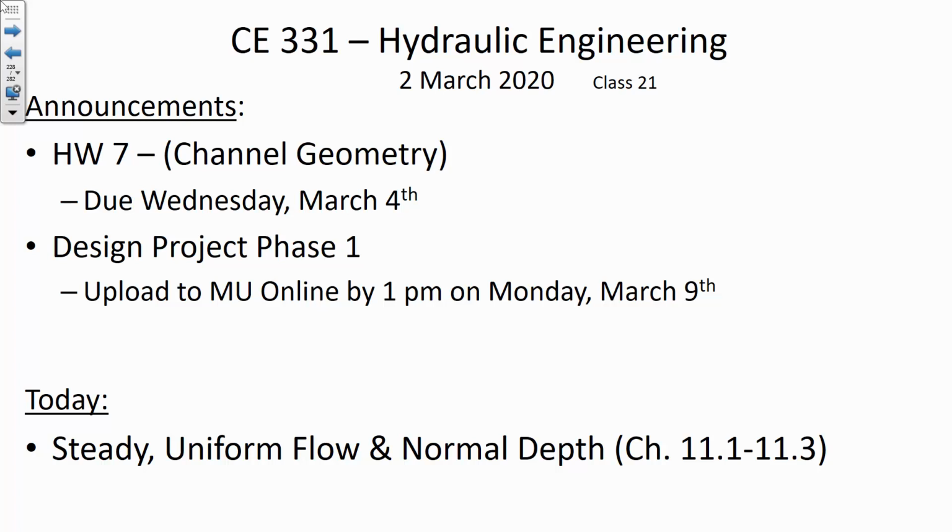So the design project is due the first phase on Monday, and that's where you're figuring out how many people are going to be in each of the zones, how much water demand there is per person, and working through that summary sheet that I've given you to identify the average flow, the peak day flow, the peak hour flow, and then combining it all together.